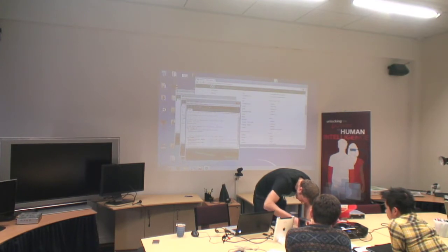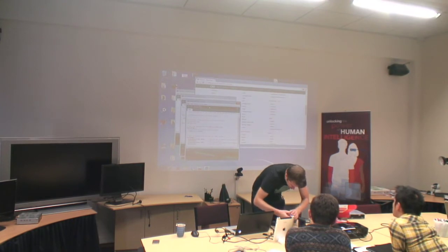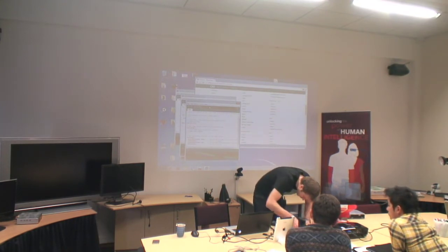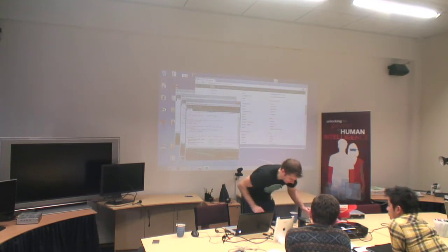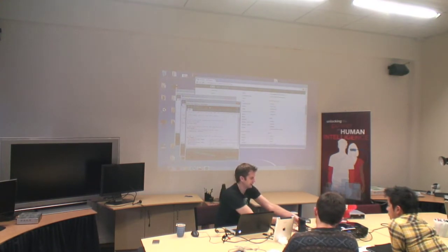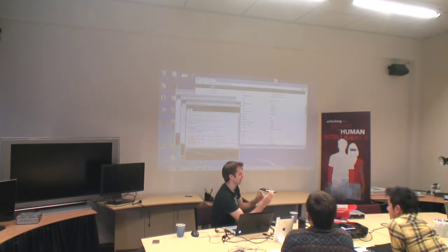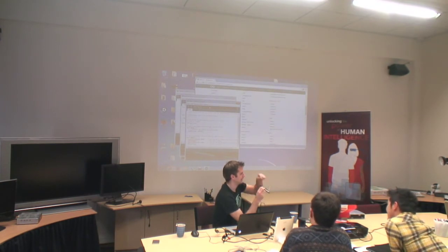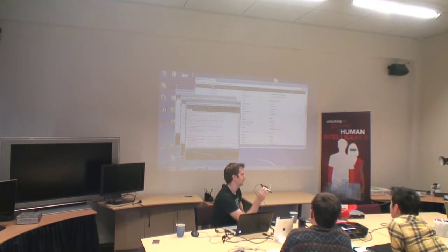That way. Now hopefully, assuming I've plugged everything in the right place, then to ground. There we go. So now they're flashing in sync, because obviously, as I said, pin 13 is connected to that LED. So if I connect an LED into pin 13 as well, they'll both light up at the same time.